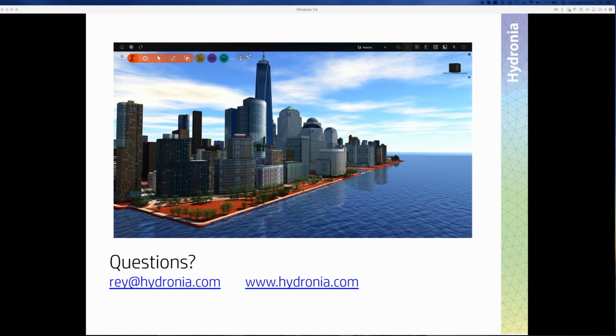Let me see if I have time for a couple more. Well, I have maybe one or two. Is there a link on the website where you can download reliable surface data? Well, not on the website, but in the SMS system, you have that tool, the one that I presented. You have a web option that you can download elevation data from many sources. Can you digitize the bathymetry from a marine chart? Yes, you can digitize the contour lines and things like that and create a scatter set out of that and use it as an elevation data set.